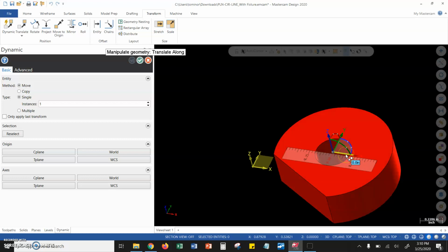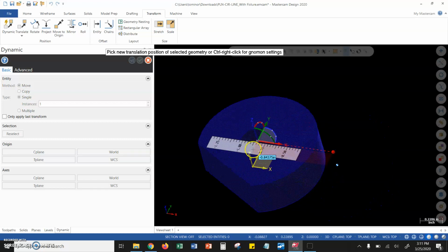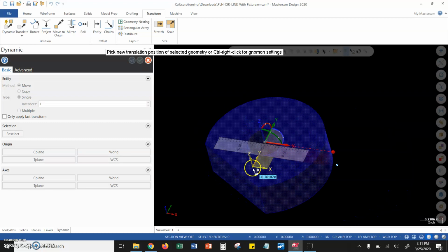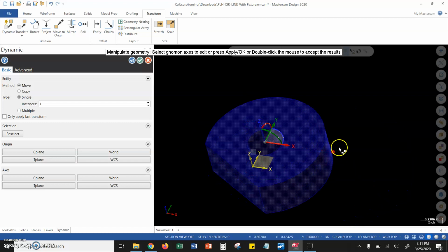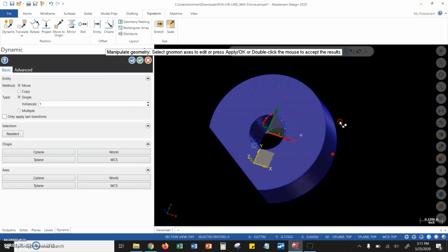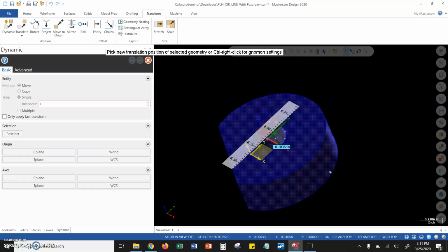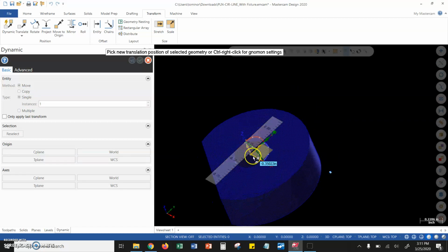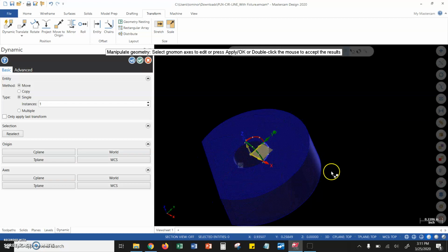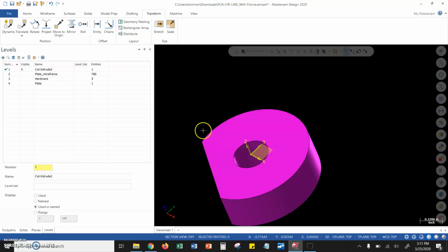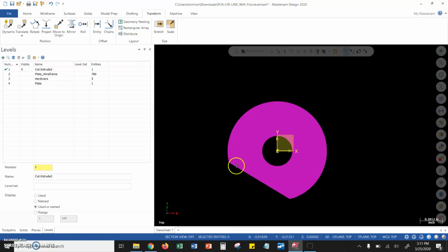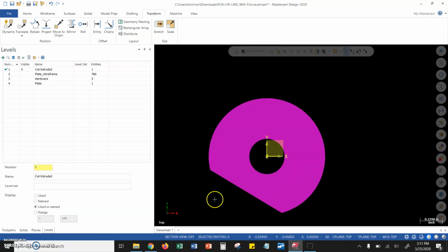So when we create the origin in the x-axis, that essentially takes our x-axis by itself and moves it over to 0. And that looks partially good, but not completely good because it's only part of the story. The y-axis 0 also has to come up to the origin. So what I've just done here is the same thing as saying create origin in x and y axis, and we say OK.